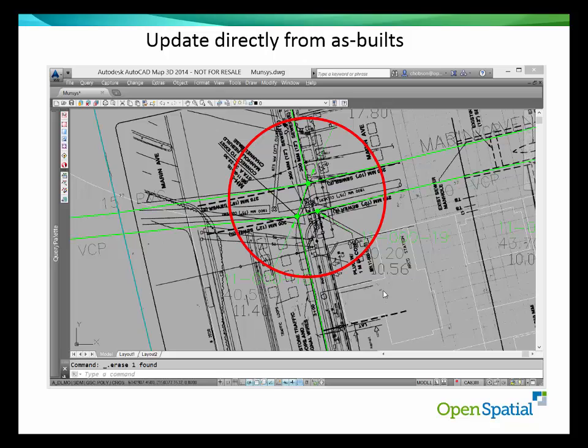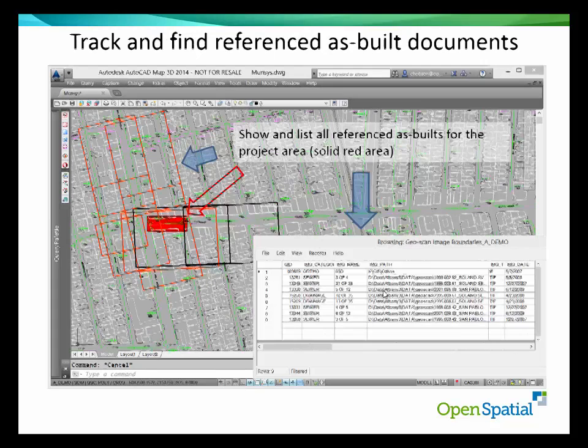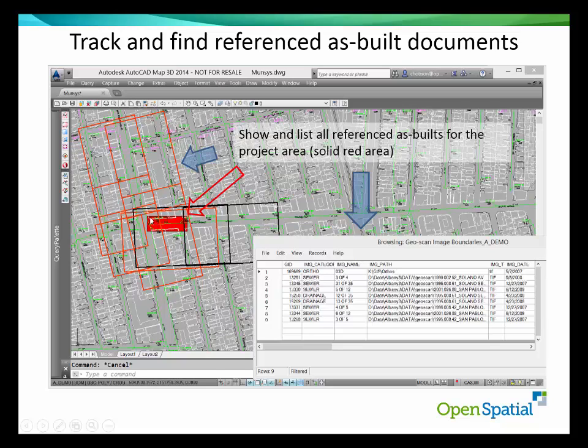More importantly, well, equally importantly, you can also use that as a spatial index, literally a set of postage stamps, so you can go anywhere in the map in future and say, what do I have on the record as plans in this area? In this screen, still in Munsys, so still in AutoCAD, I select a box where that red outline is, just to show you where we're at, and say give me all plans that intersect with that area. And what I've got is a colored-up set returned to me of red squares, which are the sewer category plans, and black squares, each of those outlines a page for a plan, the black ones being drainage. So here's a list then of all of those referenced. In 3 clicks of a button, I can go in, show the area, get a list, and run down any one of those plans and projects.